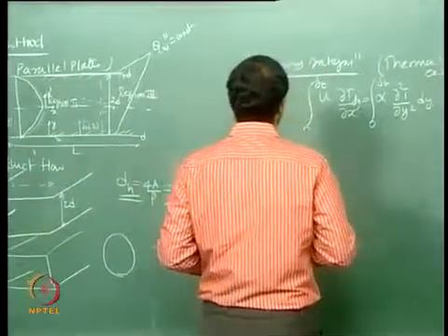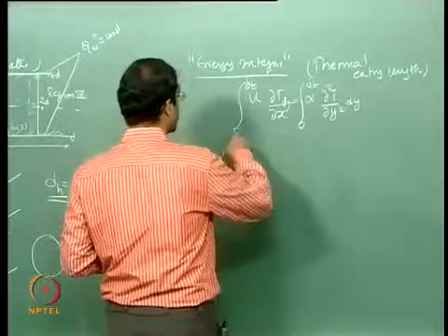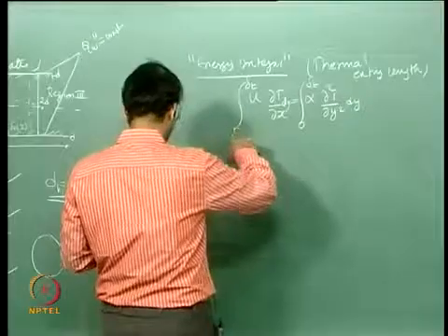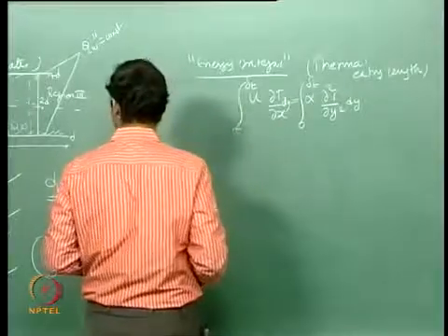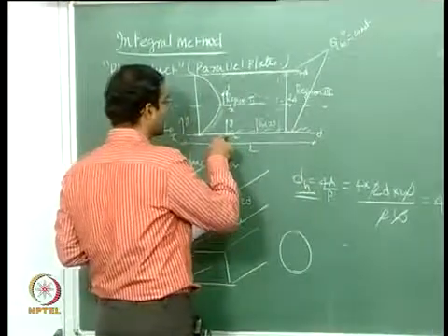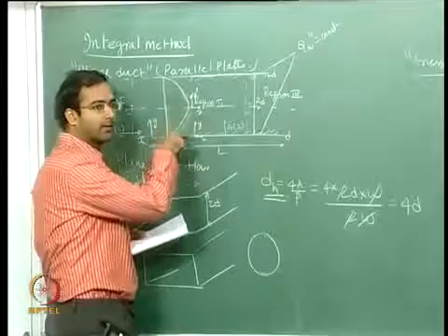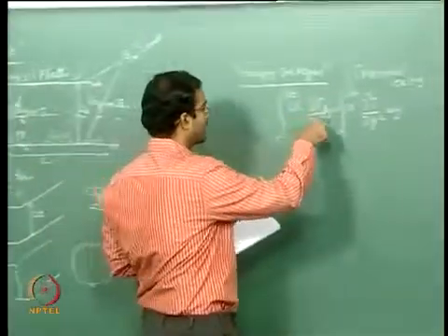And we can look at the fully developed parabolic velocity profile. So what we will do now is first start with the step and integrate it from 0 to the edge of the boundary layer. We will look at the coordinate system of y when we do this integral, not y prime, okay. So that is why I have written this as dy.